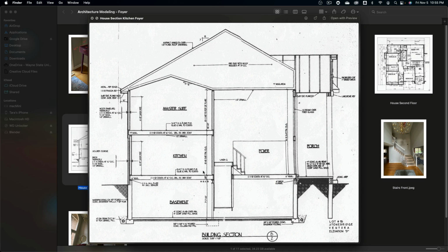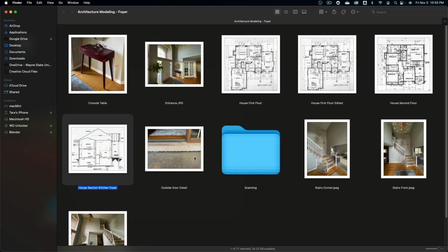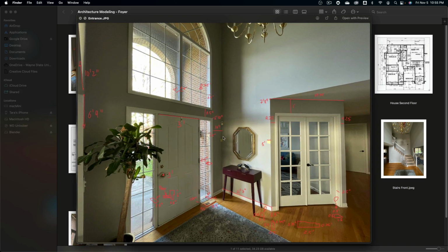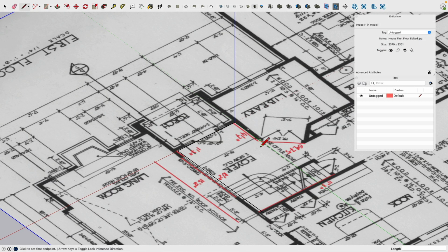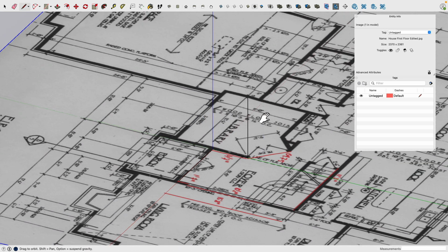Now, this is actually minus the hardwood floor that's on it. So these dimensions we even need to take with a grain of salt. So this is actually more accurate, more the as-is model or architecture. So we're going to model this edge up, and then we bring this piece over. So let's go back. So there we are. This line goes up 7 feet 11 inches and enter. Very good.